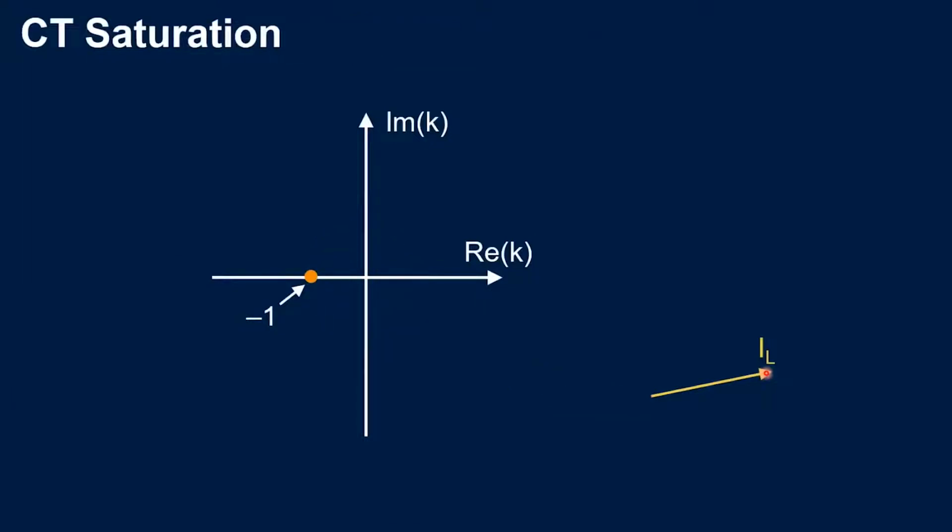We can also have CT saturation, as we were saying before. We have the local current, and let's assume that the CT on the remote end saturates. In that case, the current measured by that relay can be changed not only in angle, but also decreasing in magnitude, typically. So the operation point is going to be moving in this part of the alpha plane.